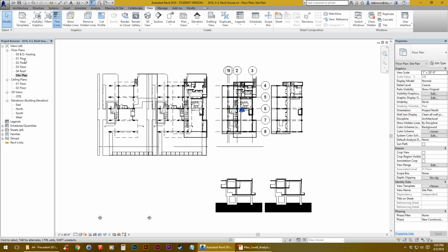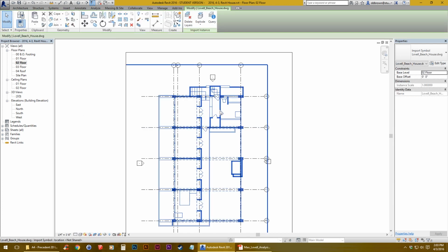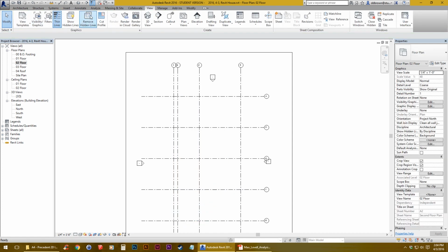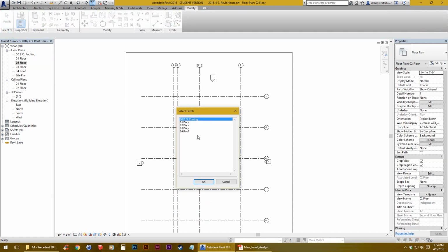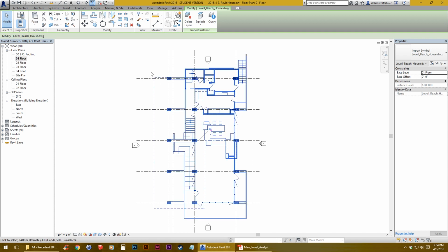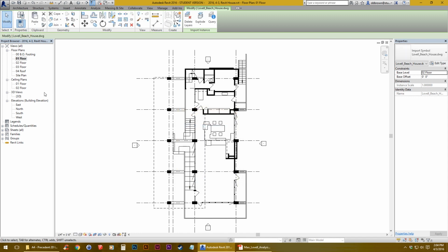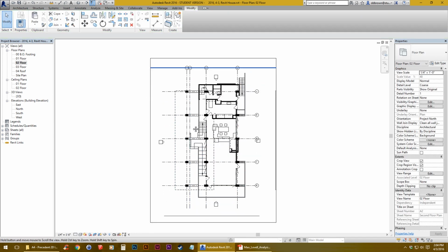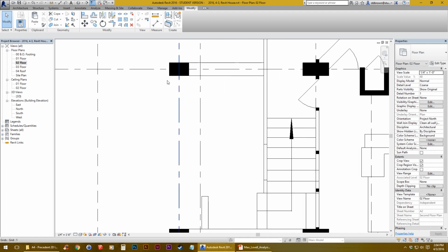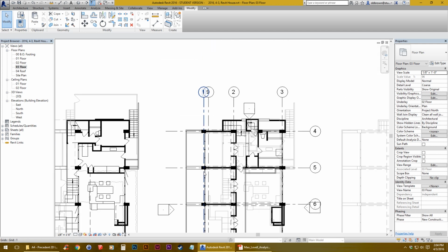But now since I started with the second floor plan on the first floor view, I want to change that. So if you go to our second floor view, I'm basically going to take this and cut it. And then I'm going to paste it aligned to selected levels to our third floor. Then jump back to the first floor. This I'm actually just going to do a copy, paste it up to our second floor. Alright, so we should have the second floor lined up. You can see there it's lined up with those columns. Third floor is lined up, that column grid with those columns.